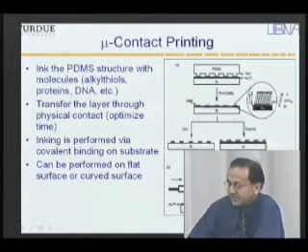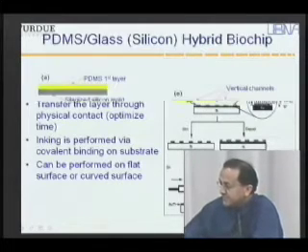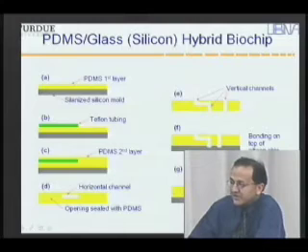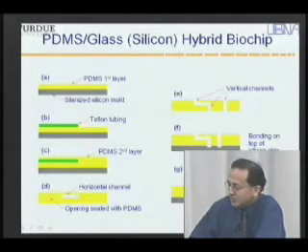One other example of using PDMS and glass to make a hybrid chip would be the following. You can take a silanized silicon mold. So you have a silicon mold here that you silanize the surface of. You form a first layer of PDMS and cure. Then you can take any other mechanical structure, like even a Teflon tubing, and use it as a mold and pour the second layer of PDMS on it. In this particular case, you can then pull this Teflon tubing out, and even close this region right here, sealing it with PDMS.